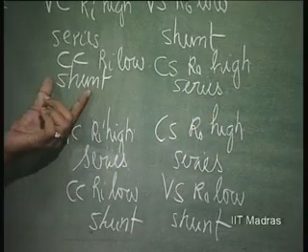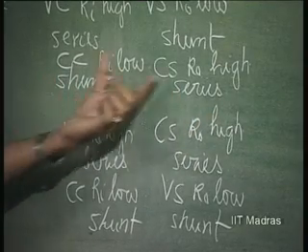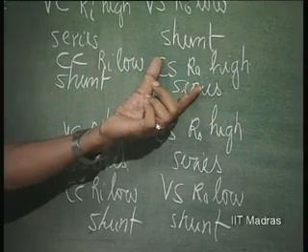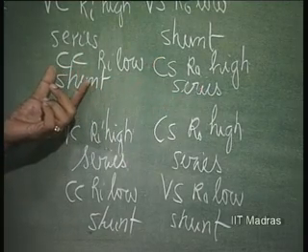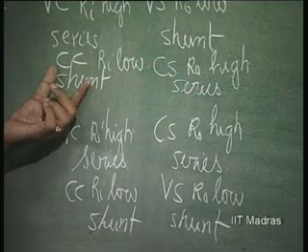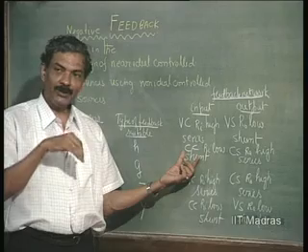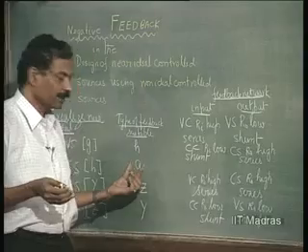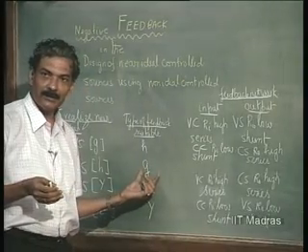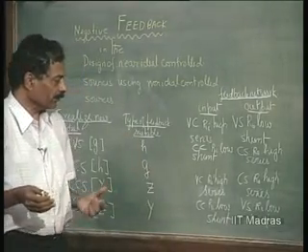So, this is shunt at the input and series at the output. Such a parameter, measured with input shorted and output open, is nothing but the G parameter, and therefore G feedback is suitable for that.